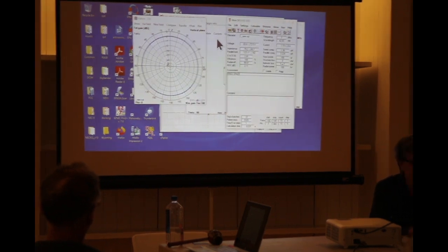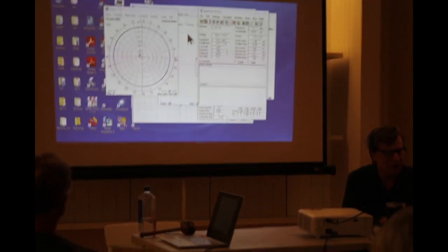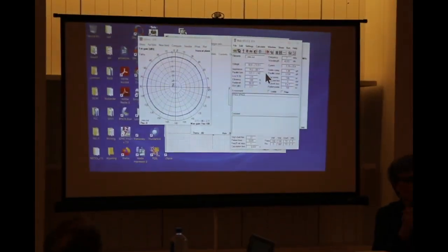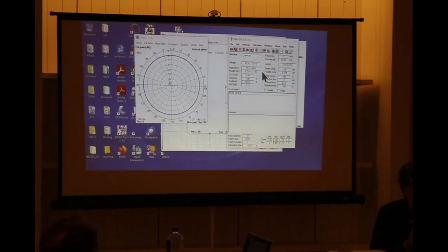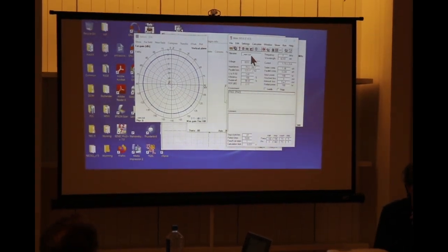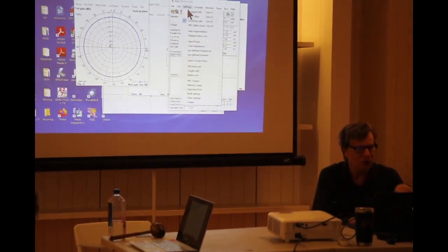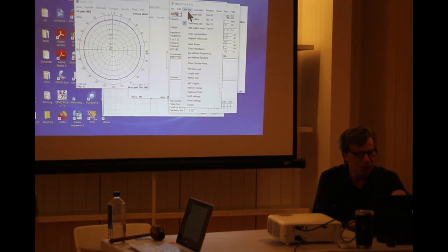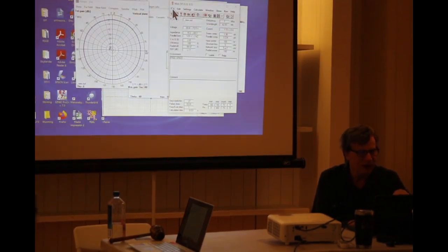Okay, so we have impedance in the ballpark of about 70.2 ohms here and minus 60.7. So let's show what's really cool about this modeling. What we have to do is change the setting here. We are no longer going to be using the graphical input, so we use a normal NEC editor here, and we'll do it this way.